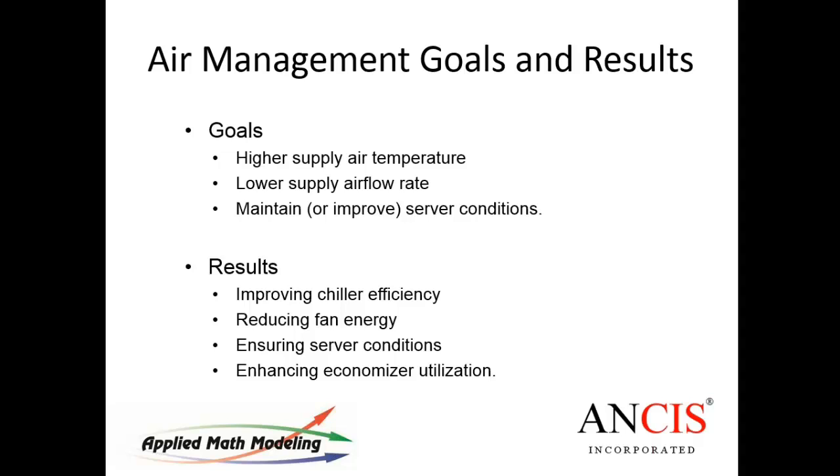So the goals with air management are to provide higher supply air temperatures and lower supply air flow rates. If you can't do these things, whatever you think is air management is not going to pay off. You need to increase the supply temperature and lower the airflow rate, and that's the only way to make it more efficient. At the same time, you want to maintain efficiency.